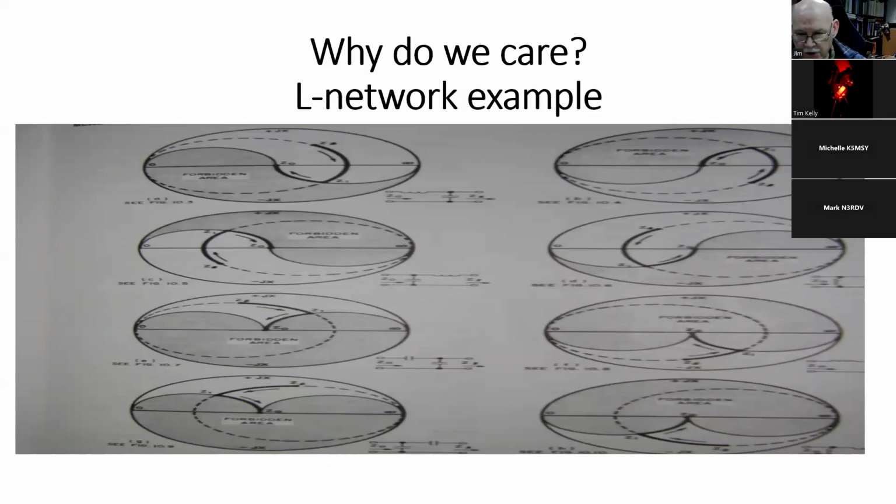And your amplifier should have a high Q output circuit and attenuate harmonics. But if you're doing your matching with one of these two topologies, you're getting additional attenuation of harmonics. So I'm a fan, and this is an opinion, guys. This is not a fact. This is an opinion. I'm a fan of these two circuits.